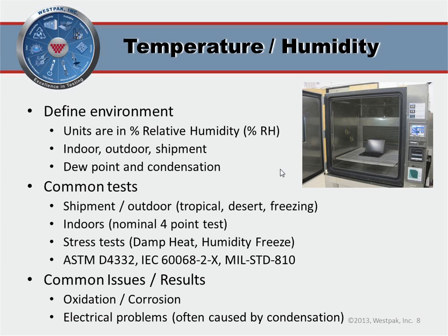Thank you, Herb. One last thing to add on this is when you specify a test plan, generally we don't control any humidity level below 5 degrees C. And from a test standpoint, the colder things are, the harder it is to control humidity. And a final parting thought: you're in a temperature humidity chamber, and generally the chambers can run both types of conditions, so think about combining your test plan and putting as much as practical in the chamber to get the most value.